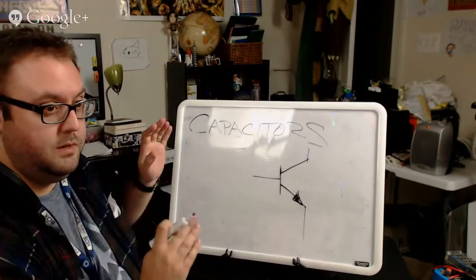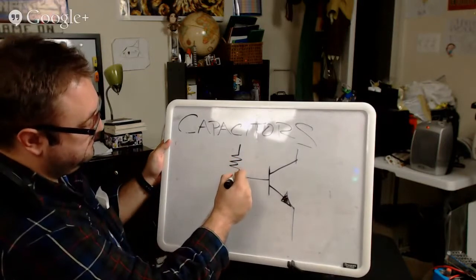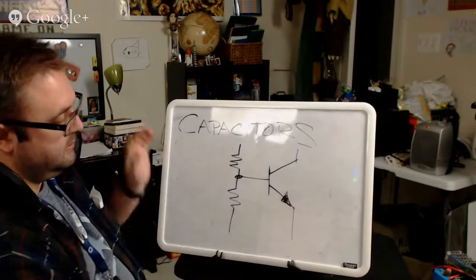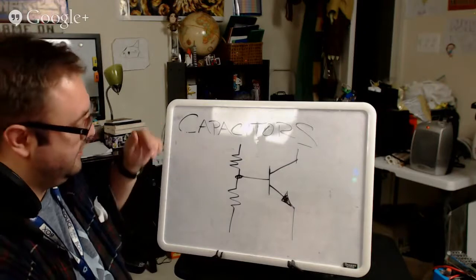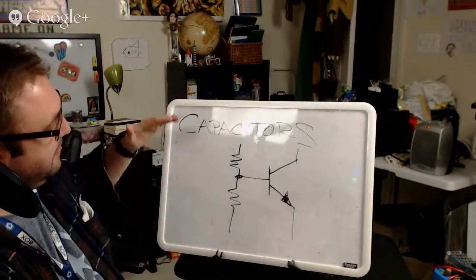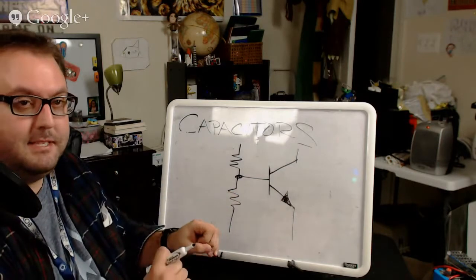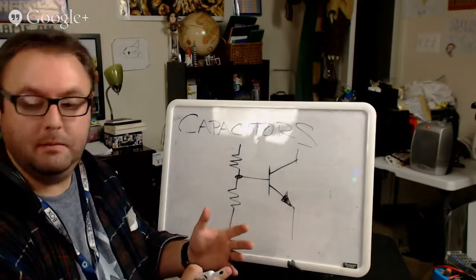You don't have to really know much about it at this point, but say we want to amplify our voice, an audio signal that alternates. The transistor has to be what's called biased. That means it's got to be given enough DC voltage to kind of turn it on.